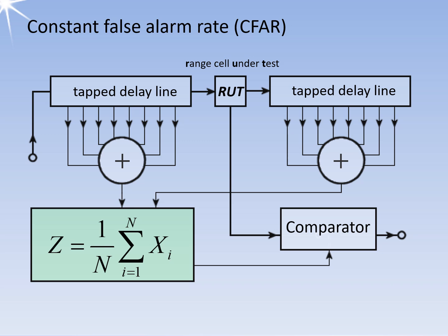The equation for forming the average involves adding all the voltage values together and then dividing by the number of values, n. Analog radar signal processing requires real delay lines, while in digital radar signal processing, these are essentially neighboring memory addresses for storing the echo signal amplitudes.